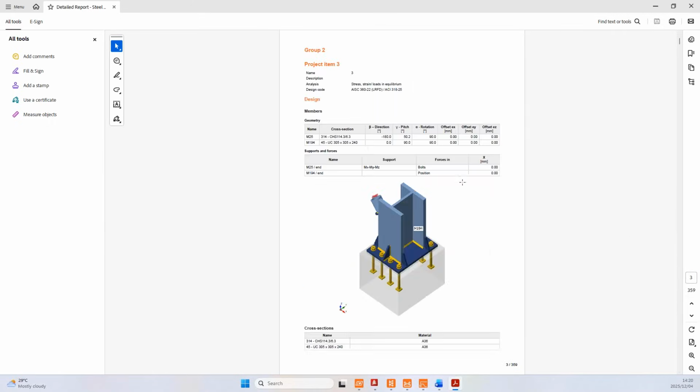So all of those code checks that we have undertaken so far in Checkbot are fully integrated, and we can see that everything is code checked correctly according to the standards. So that's basically the demonstration of the workflow from BIM link to StatPro, and then from there it goes to detailed 3D for the consideration of reinforcement in the anchoring.